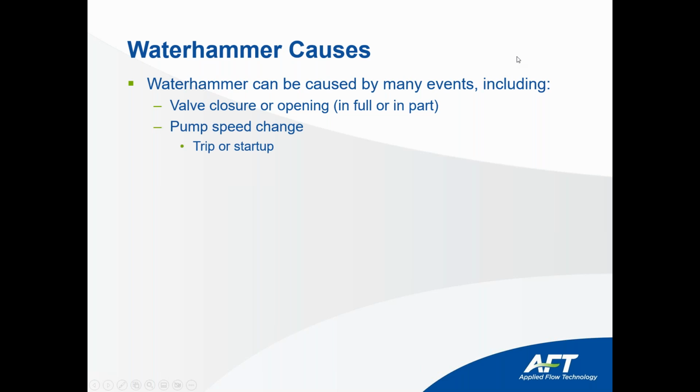Not only the trip or the startup of the pump can generate Waterhammer, also pump speed change can generate Waterhammer in your system. Relief valve crack opening is another possible source of Waterhammer effect. And another one that can cause Waterhammer effect is a rapid change in tank pressurization.